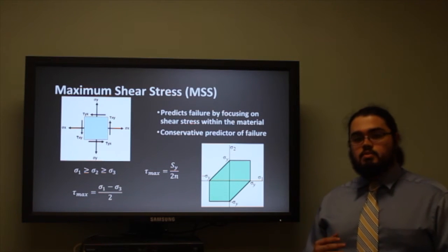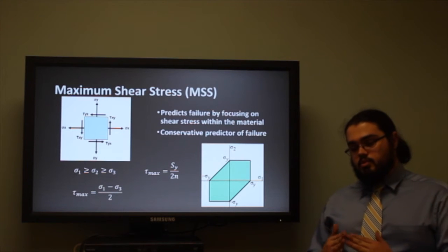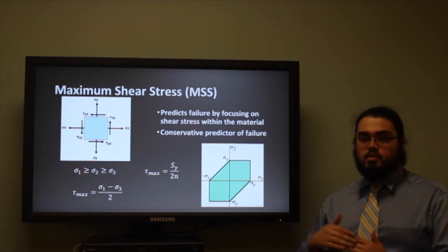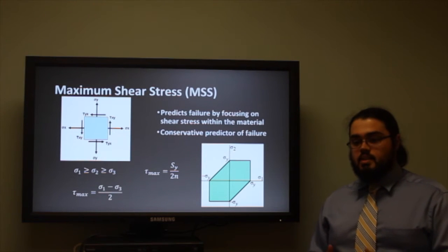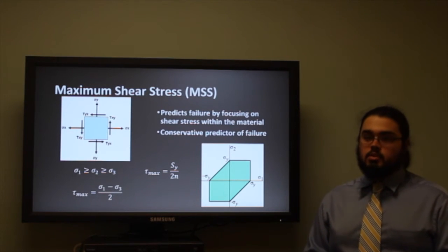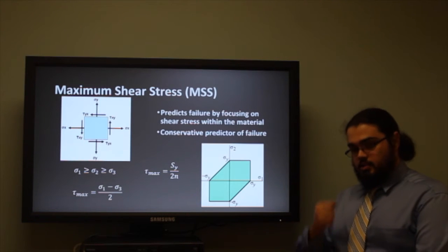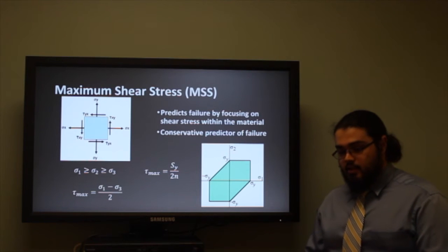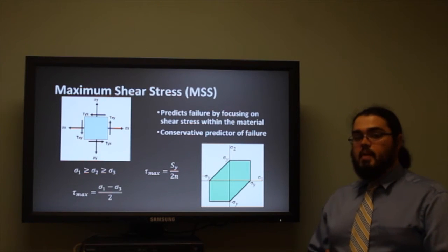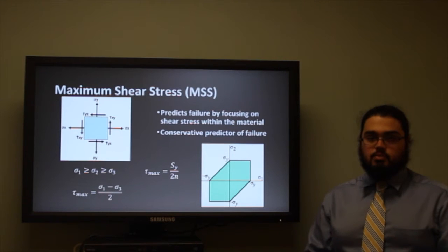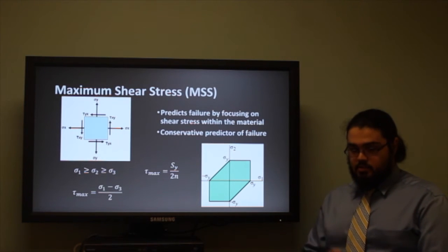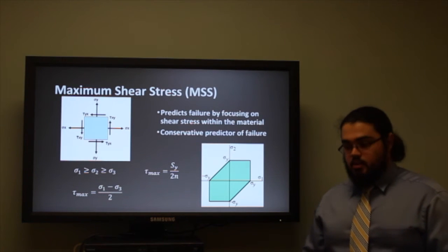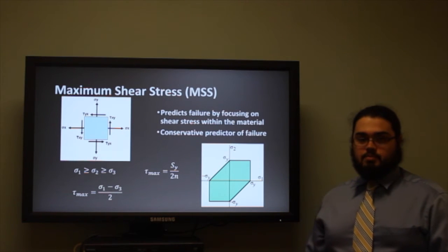when necking occurs, inside that necking point, there's these things called slip lines that are the signs of the plastic deformation. These slip lines occur at a 45-degree angle to the tension axis. Okay, and it also so happens that shear stress is a maximum at a 45-degree angle to the tension axis. So the hypothesis is that failure is the result of this shear stress.